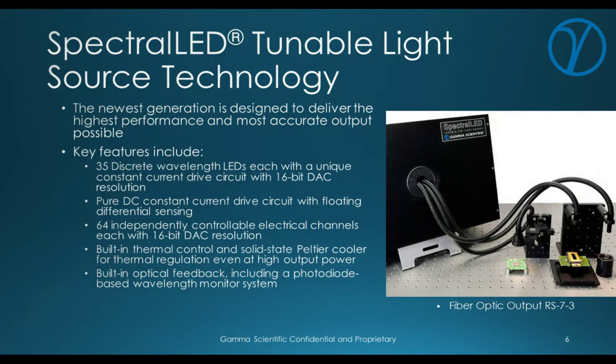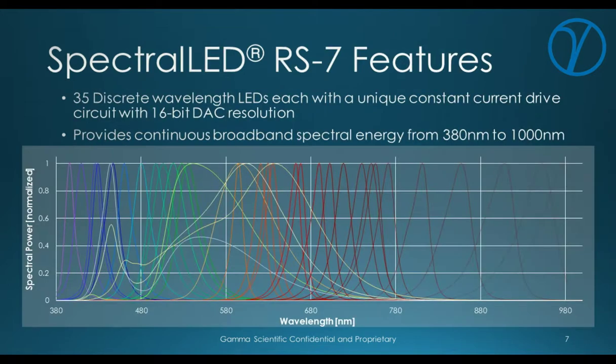We also have a built-in thermal controller with a high-power Peltier cooler. This allows us to keep this large array of LEDs temperature stabilized, even when we're working at very high drive currents and output powers. And there's also an optical photodiode for real-time feedback to maintain the amplitude and regulate the output.